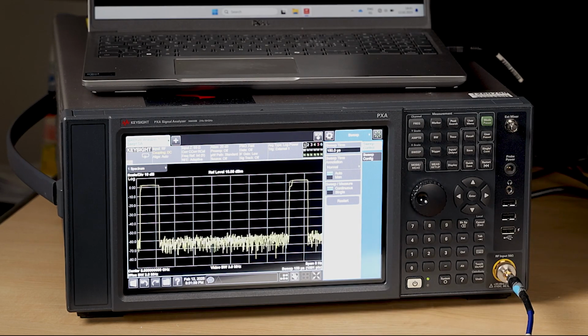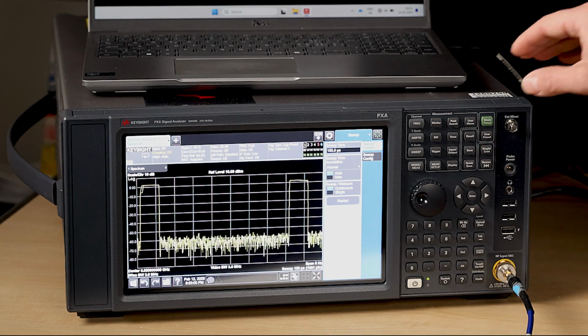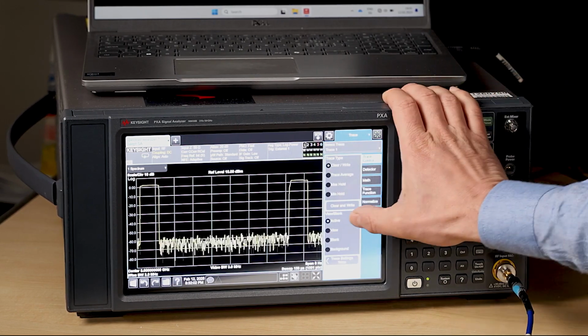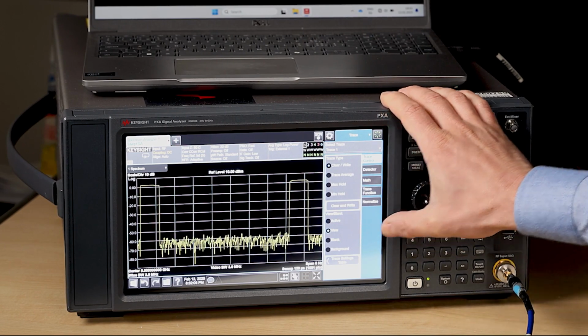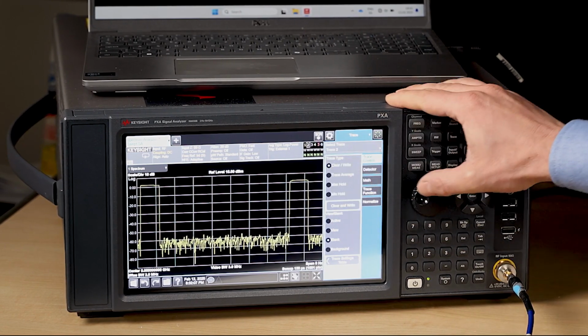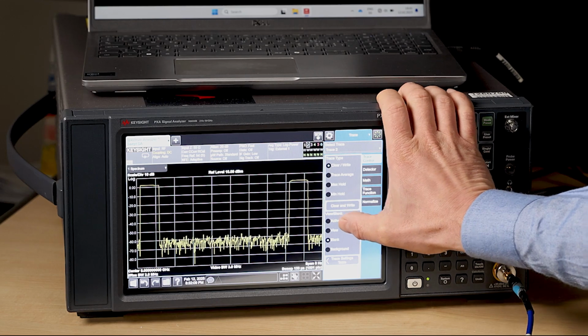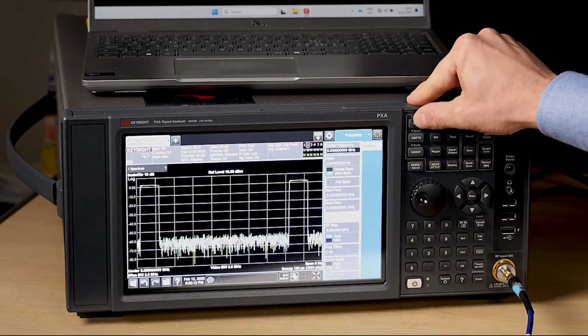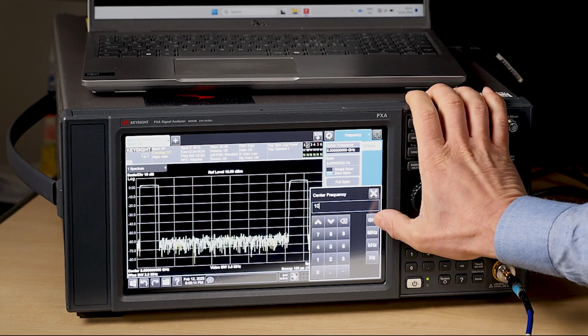So we can see that the spectrum analyzer starts its capture exactly when the sweep restarts. We can now see the first pulse of the sweep right after the spectrum analyzer starts its sweep, and we see the sweep repeat after 120 microseconds. On the spectrum analyzer, I can now hold this trace and use further traces to verify the timing of all the individual pulses.